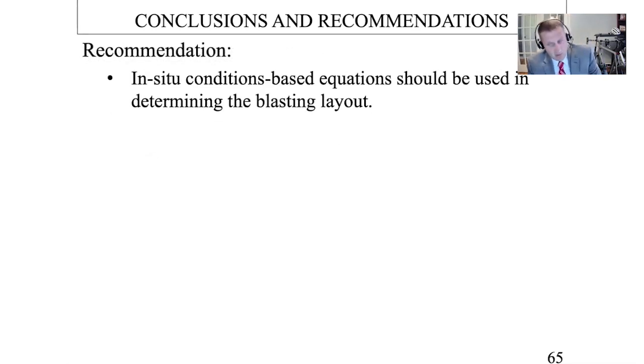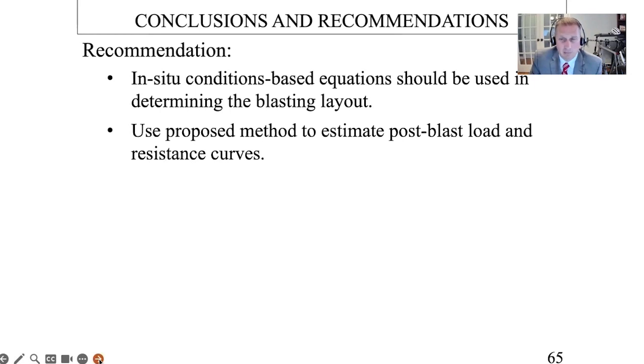So some recommendations and conclusions that we have here, specifically related to the in situ conditions, should be used to determine the blasting layout. The proposed method is used to estimate post-blast load and resistance curves, so you can do that before you blast and then compare them. And this was all on single piles.